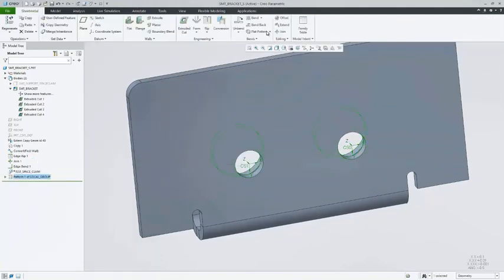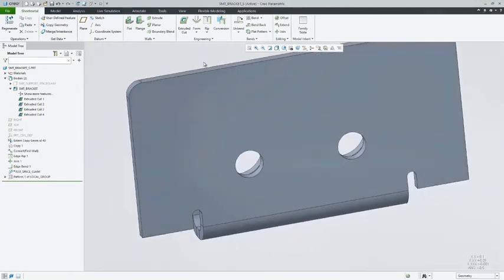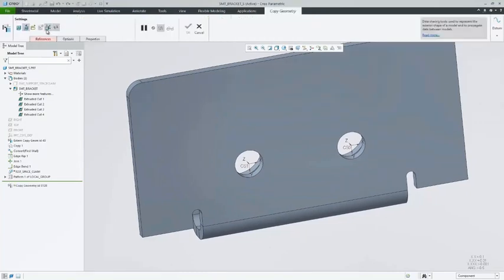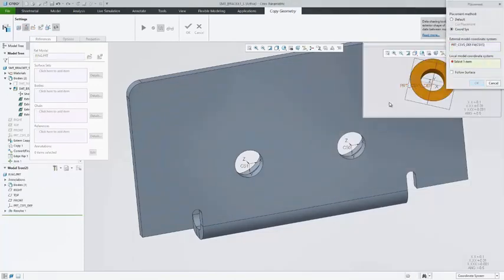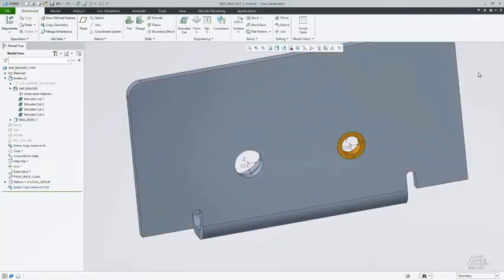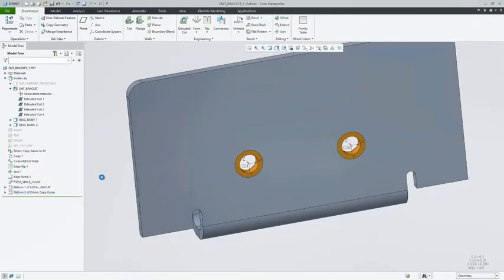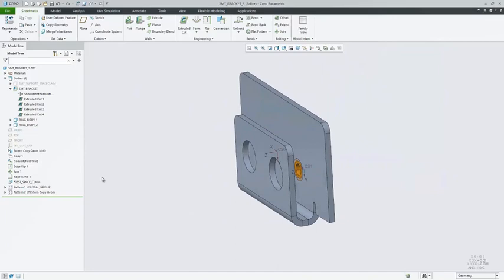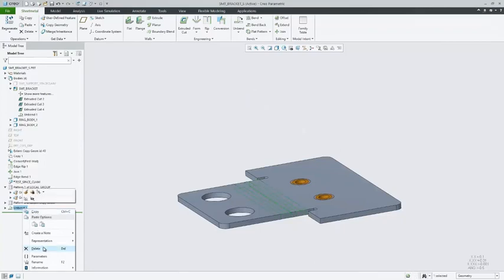They can be created within the sheet metal part design environment or inserted using data sharing features such as external copy geometry. The external copy geometry tool offers a follow surface option. Select the follow surface checkbox so that inserted bodies follow the bend and unbend operations on the sheet metal body. Unfold and flatten operations themselves only apply to the sheet metal body though. Use the Boolean operation subtract to subtract geometry of the selected basic solid bodies from the sheet metal body.